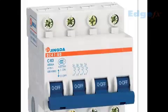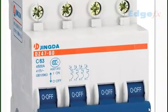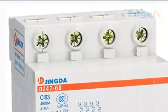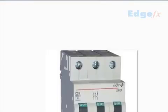We also have another type which is called a TPN, that is 3 plus 1. The 1 is for the neutral, but it is advisable never to use TPN. TPN is for certain specific applications. It is always better to use the 3 type and not the 4 type. The 3 type means what we had seen, this one. We should use this one and not the 4 type. So this is the protection device requirements for the